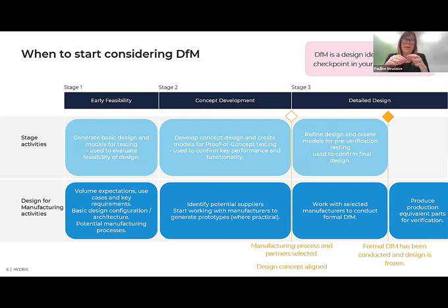So I guess there's design for manufacturing as an ideology, of getting all the insights and input that you need throughout the process. And then there's a formal design for manufacturing activity at the end, where you then, with the selected supplier, go through all the details of your design. This is usually where the supplier will spend a significant amount of time doing mold flow analysis, for example, if it's an injection molded part, and doing some of that analysis that gives you those final adjustments to a design.